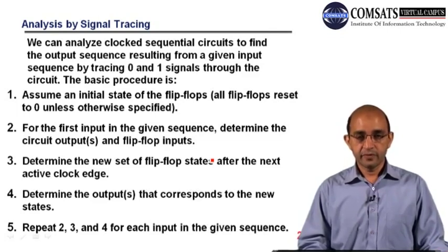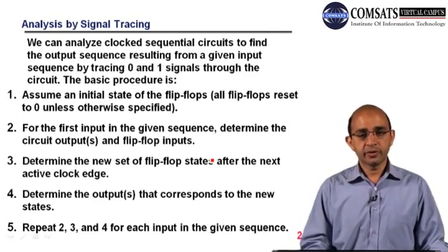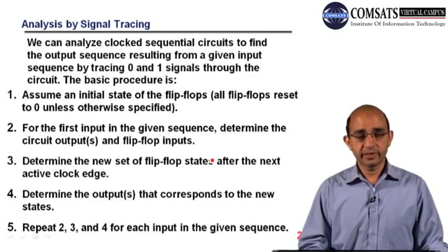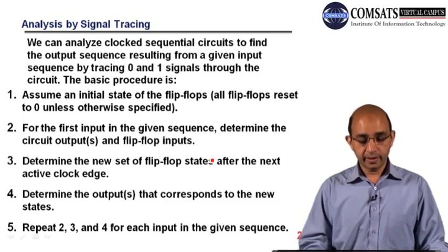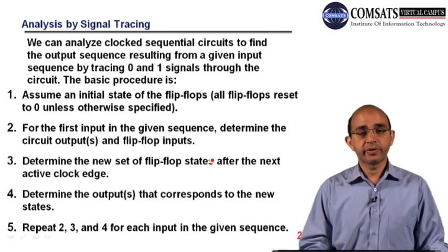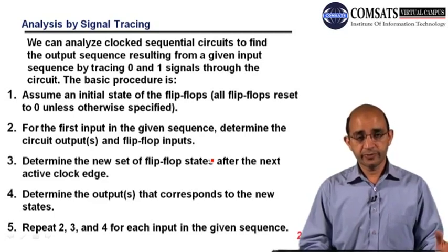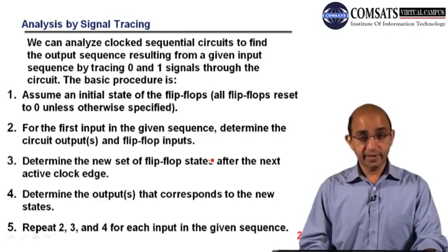First, we have to make sure that all the flip-flops or memory elements are at the zero state, meaning we have to reset them. Then we have to determine the input and the output. The input is regarding the input to the flip-flops, the memory elements, and the output is regarding the overall circuitry output.